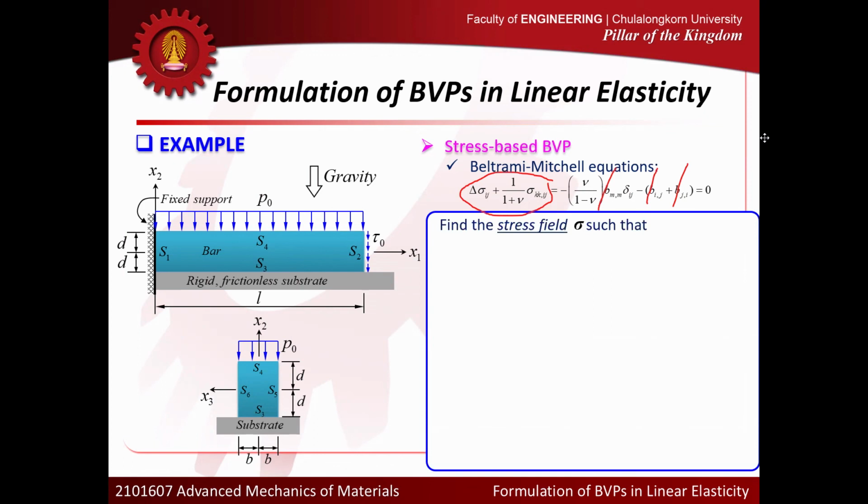Don't forget that for the stress-based formulation, we require not just to satisfy the Beltrami-Michell equation, we need to make sure that stress is in equilibrium with the body force field. So in this formulation, we need to satisfy two sets of equations. The first one is the equilibrium equation, and the second one is the Beltrami-Michell equations.